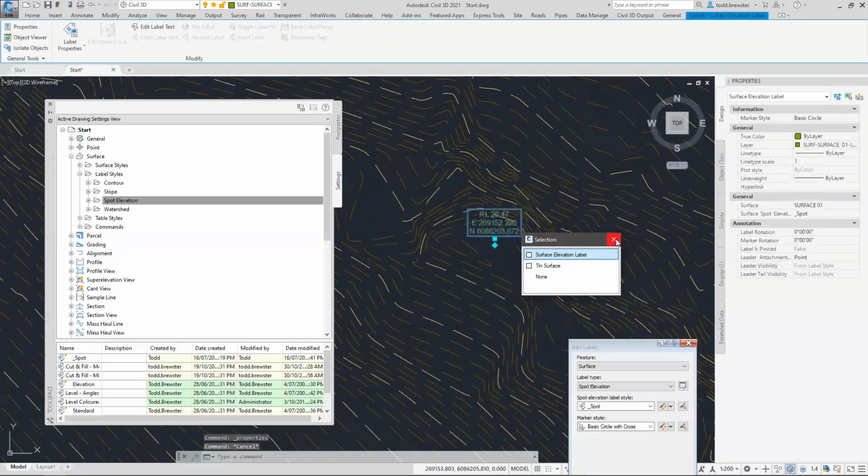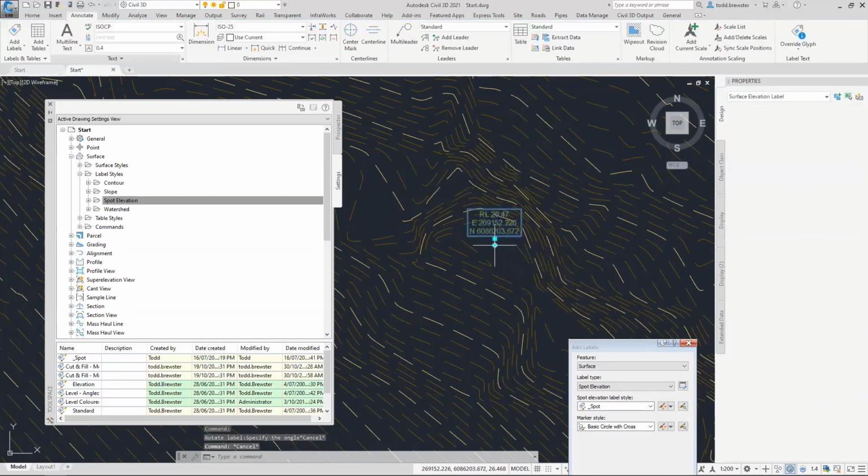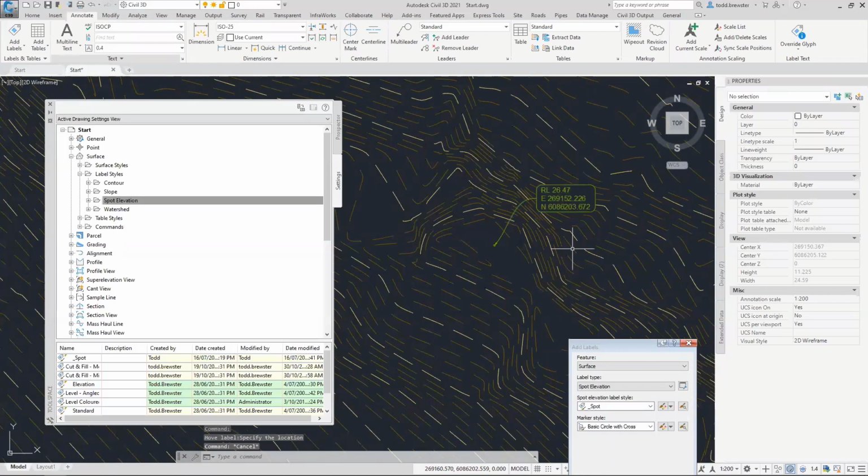That rotation that I was talking about in terms of plan readability, if I actually rotate my label, as I spin around over 95 degrees, the text in the label will flip back. That's keeping it readable. So that's what I was referring to in plan readability. It applies to all your label types. The drag state, if I then grab the label and drag it off, it'll jump into drag state mode.